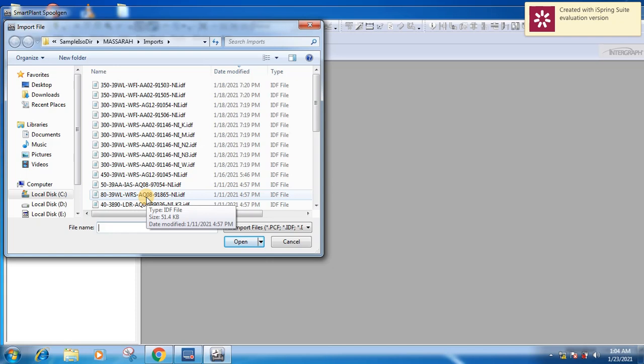So each and every setting is decided at the admin stage while creating a project. So that is a separate task. So we are talking about when we have created the project and now we are importing an IDF. Here we can see the software can take PCF, IDF, DAT, MOD, SUP formats. These formats are generated by different 3D modeling tools.